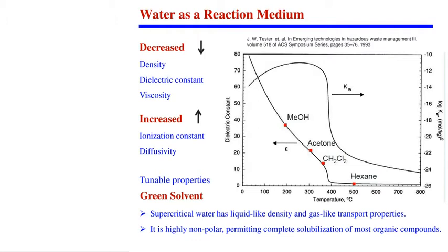We can have a biomass and water pumped as a slurry. We can have a hydrothermal reactor where we do the liquefaction. The solid fraction which comes out is called char, and the liquid fraction, crude fraction, and some gaseous fraction will separate out. The crude fraction will look like a petroleum crude, but it's not yet ready for liquid fuel application, because it needs some more hydrogen to be upgraded and remove oxygen, so catalytic upgradation, and we get naphtha hydrocarbon fuels.